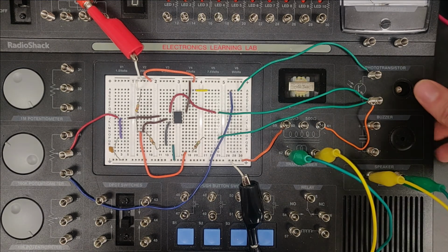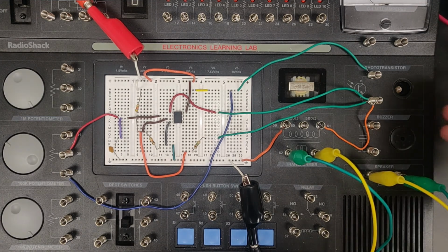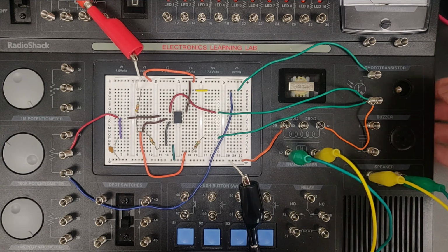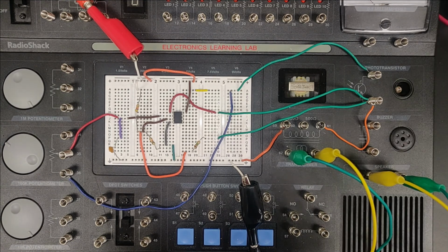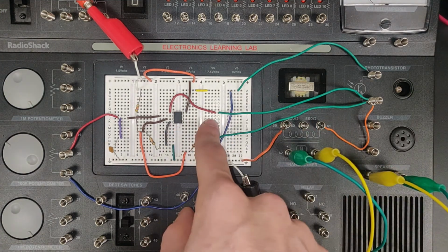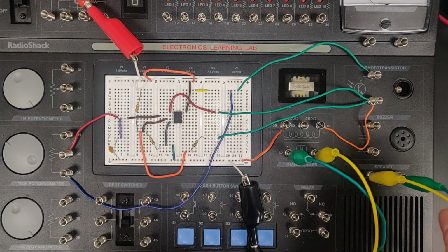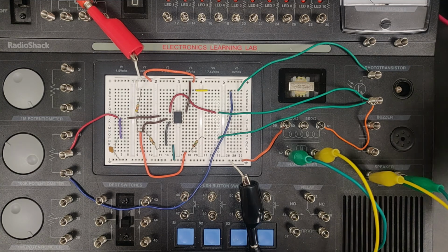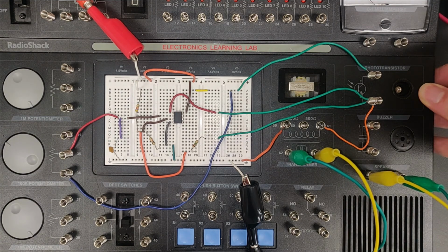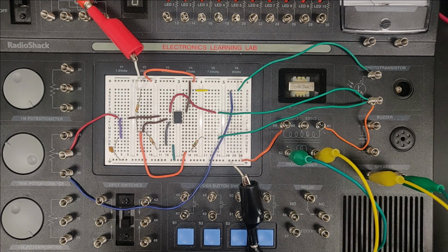And over here is our phototransistor, so it outputs a small signal depending on the amount of light that it is receiving. Down here is our transformer, which is taking our signal from our op amp that's being boosted and transforming it over to where the speaker is down here. So it's taking this small AC signal from our phototransistor and turning it into a mechanical wave that we should be able to hear.